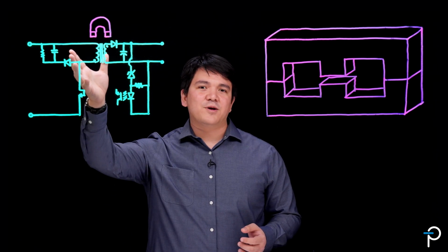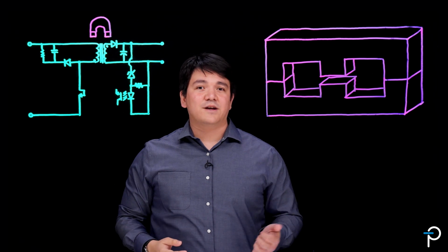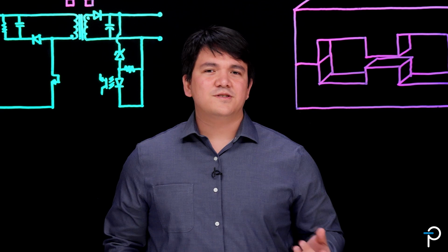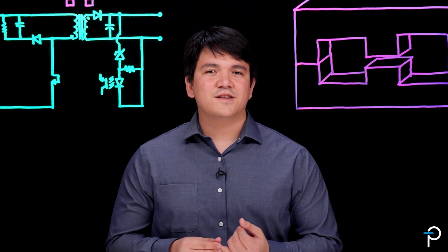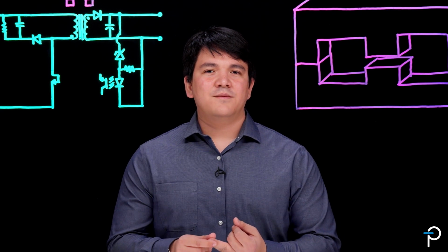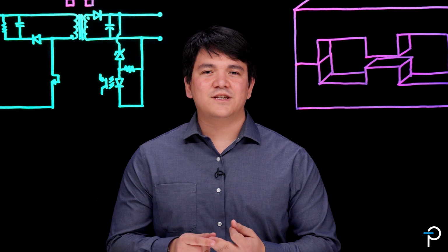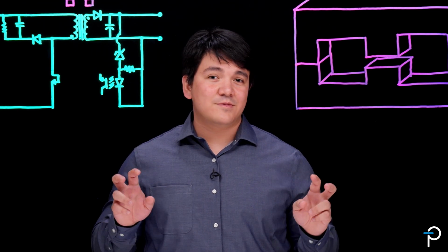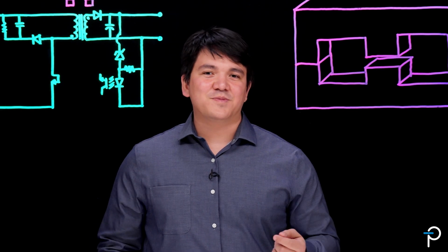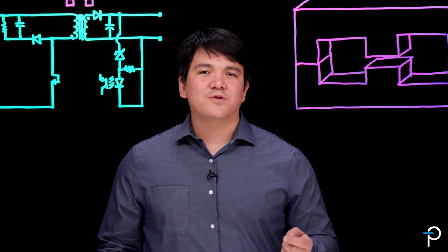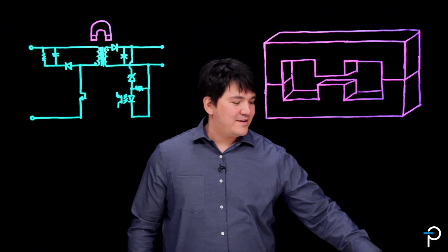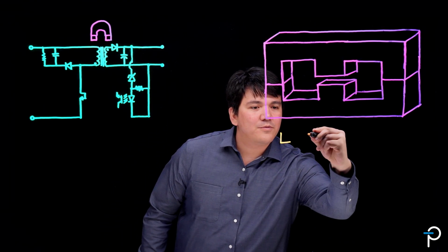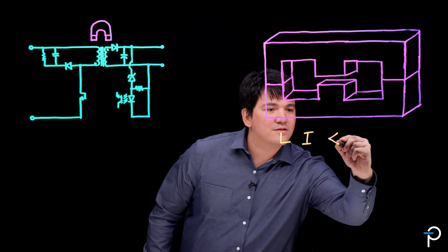Now, we can't do anything about the magnet, but we can certainly do something about flyback design. In flyback design, some considerations involve MOSFET and component selection, PCB design, controller scheme, but arguably, the transformer is at the core, center, so to speak, of being able to meet critical performance requirements. When designing your transformer, we usually use this equation.